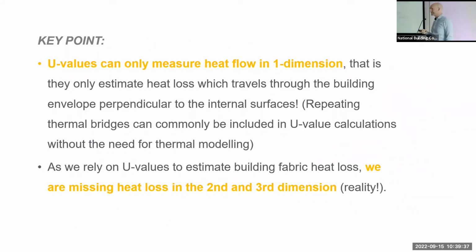There's a key point on this. It all really harks back to how we carry out a DEAP assessment to demonstrate Part L compliance overall. A U value, or the equations that we use to calculate U values, can only account for heat loss in one dimension. They cannot account for two-dimensional and three-dimensional heat loss. That can only be done with finite element analysis, which is basically numerical thermal modeling. Again, you might have an SFS stud in a wall and the heat flow will change there, but in the U-value calculation, ultimately, it's only calculated in one dimension. An accurate calculation would be a 2D or a 3D calculation of that.